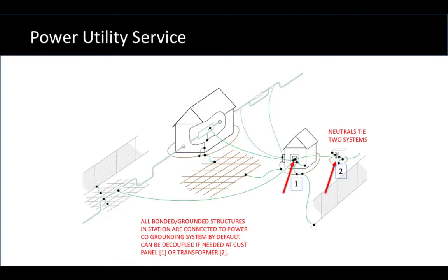There's another solution that can be done by the power company at the transformer because they own that part of the system. And if appropriately installed, again, a subject much too broad for covering here, you can have acceptable CP isolation and yet meet all of the safety bonding needs of the tie between those two systems.